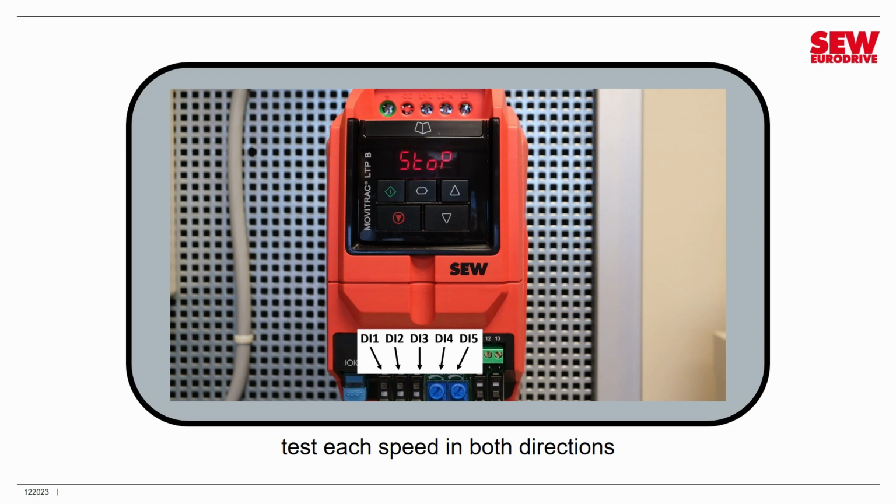Of course, I have 2 potentiometers connected up to my analog inputs 1 and 2, which also are digital inputs 4 and 5. I will be using both of these not as analog devices, but as switches. Remember, if a potentiometer is turned all the way down, it's like an off switch, and if it's turned all the way up, it's like an on switch. So I will be using these purely digitally. They don't actually control the speed in an analog way.